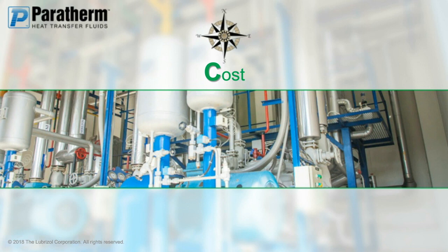We said mineral oils, natural organic hydrocarbons have certain extreme minimums and maximums, and the aromatic or synthetic products allow you to extend that to a higher range. So it becomes critical to really analyze that when you're right at the extremes of those limitations.